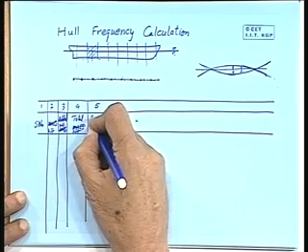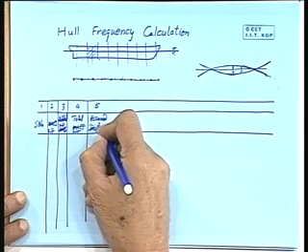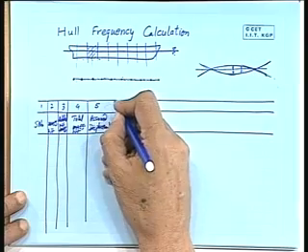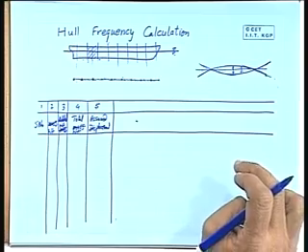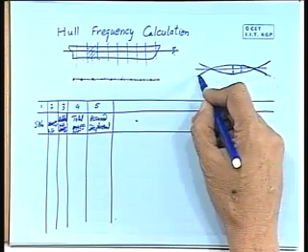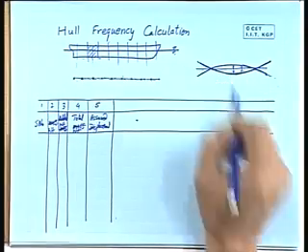Then you take assumed displacement. Okay, we take some assumed displacement. Now you can take this as an assumed displacement for a free beam. So normally what is done, you take a uniform beam, and for the uniform beam you consider a free beam displacement curve, knowing fully that a ship is not a beam of uniform cross section.